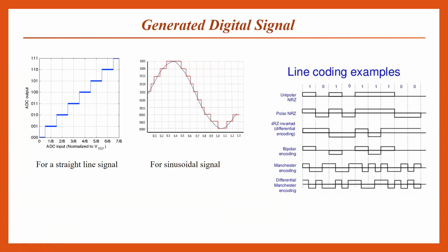1010 cannot be transmitted directly, we have to provide it in electrical form. Only electrical signals will be transmitted through the transmission channel. So this conversion of logical form into electrical form is called line coding. 1010 is not a sequence we can transmit directly. We have to provide the electrical form, or we can say voltage levels, to our particular bit sequence, and then transmit it through the channel.